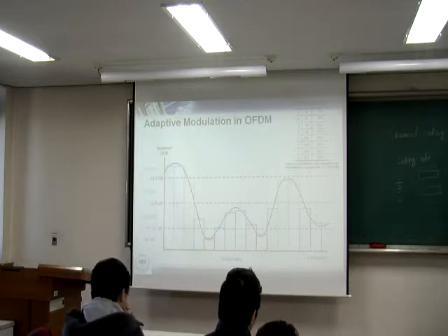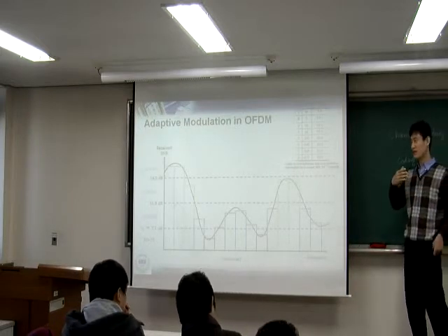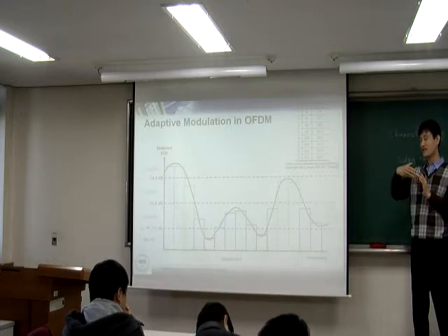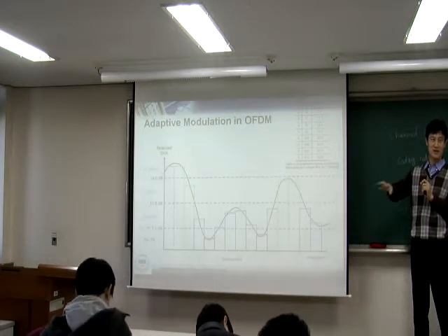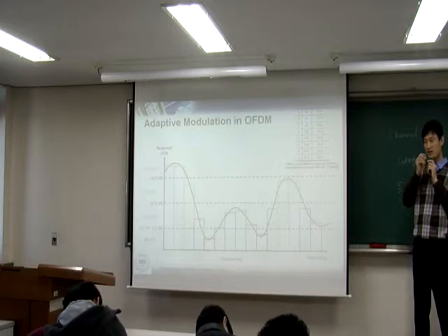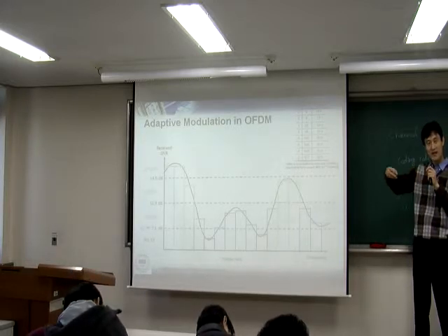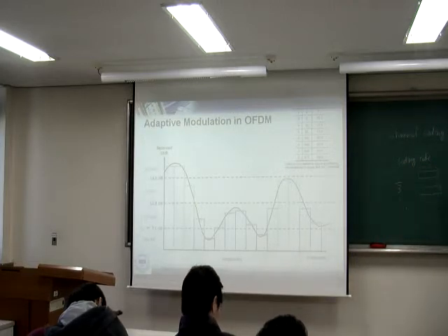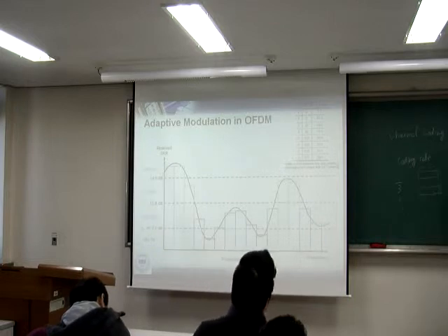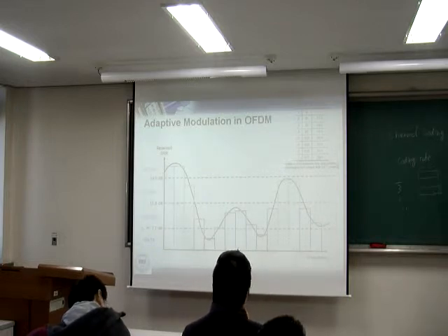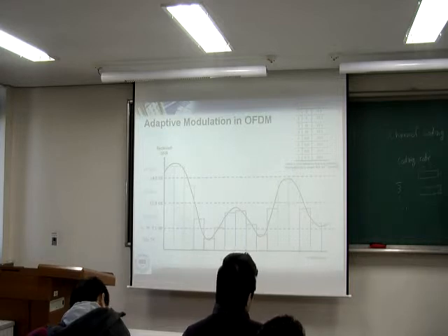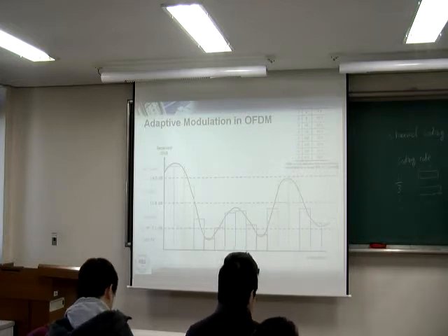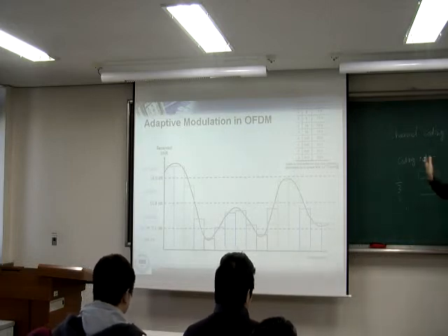Because there is a lot of multipath and a lot of intersymbol interference in a telephone wire. When you talk, your voice has a lot of delay, a lot of echoes. There are a lot of echoes in a telephone wire. Therefore, you need very, very excellent equalizers. Equalizers can never cancel out your echoes. They will reduce them, but there's a certain limit. The best you can do is try to reduce it. You want to use multiple taps.